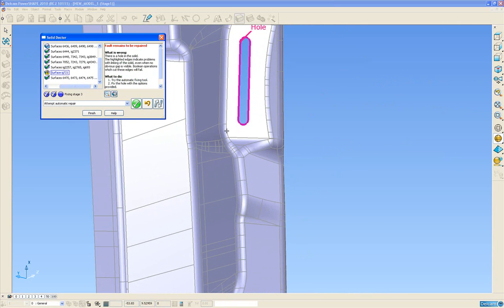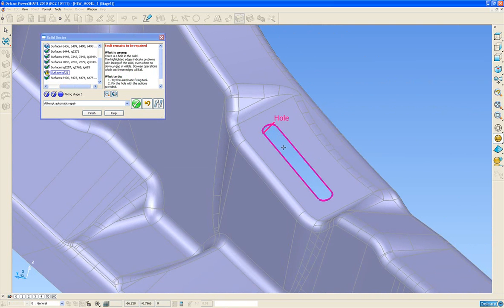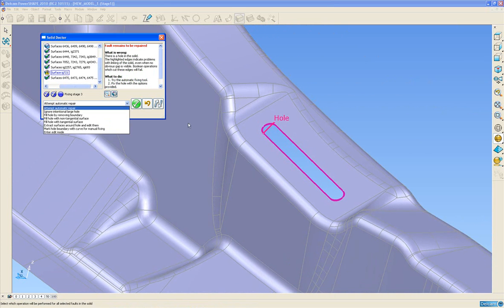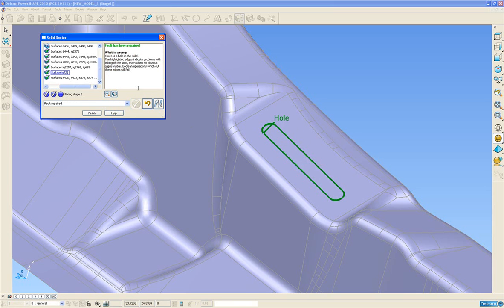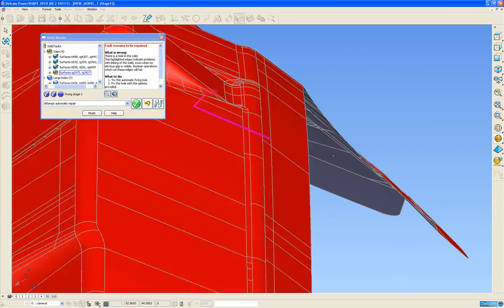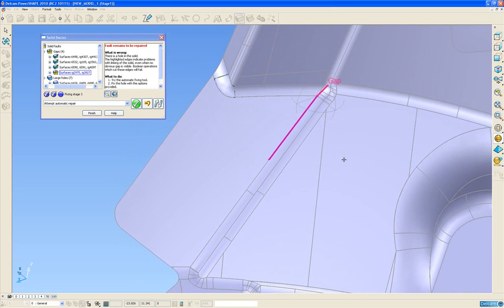Okay, moving on to the last of our large holes. Again, this is an intentional hole in the part, but still needs to be filled in for manufacture. But this time it's a planar surface, so we can simply remove the boundary of the surrounding surface, like so. All that's left now is one remaining small gap, in this region here.